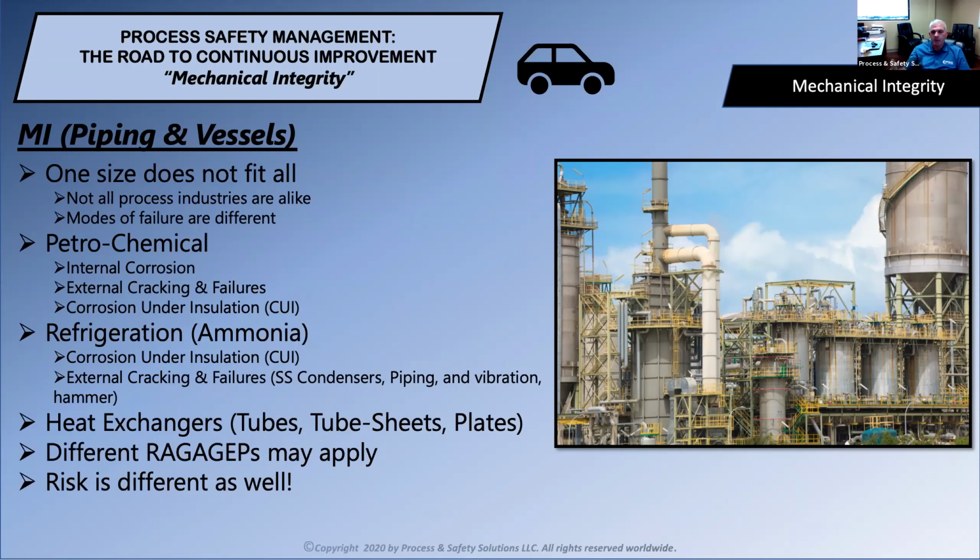Depending on the materials that they use, acidics and caustics can attack the metal surface itself, not only corroding the surface, but also causing external cracking failures as well, especially in and around equipment such as cooling towers. We see a lot of cracking. We see a lot of external corrosion as well that has to be addressed.